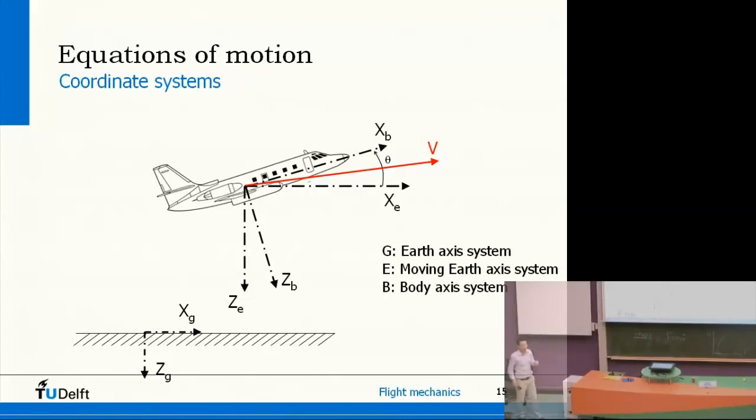And the most commonly made mistake is that you think that the airplane is following its nose. It isn't. This airplane, as it is oriented now, could actually be dropping out of the sky like this. Then the airspeed vector would be pointing downwards. Now, that is typically not the case, but as you see here, this is more a typical case.